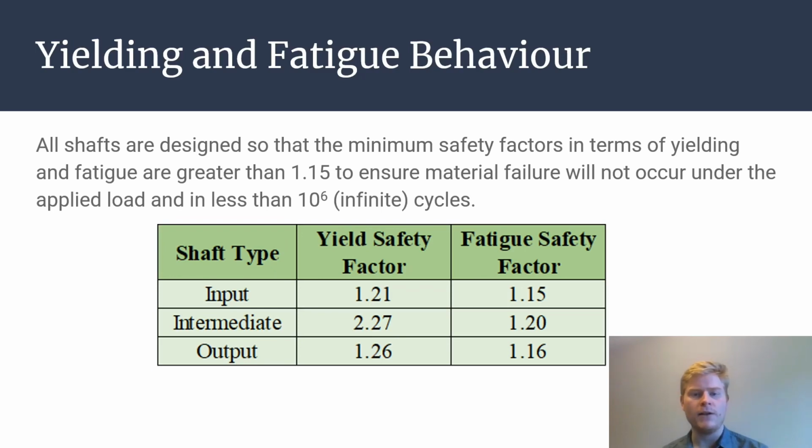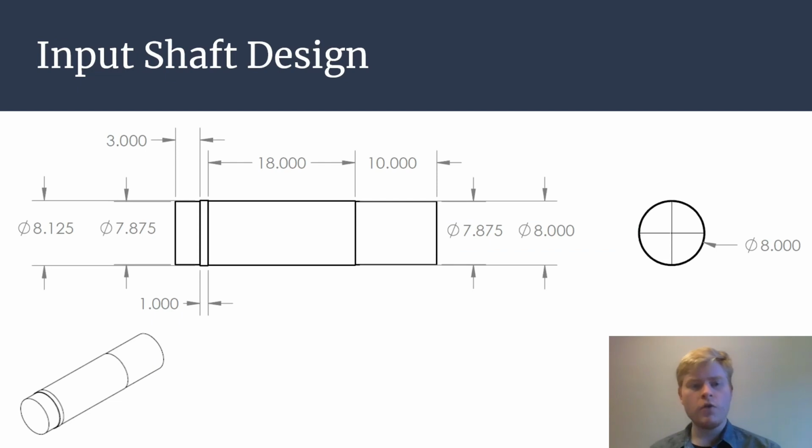1 megawatt of electricity. Moving on to the physical drafts of the components, all shafts are designed to minimize mass and to ensure the design is cost effective. The shafts are machined from high-strength AISI 4340 steel. The input shaft can be seen to have an overall length of 32 inches and possesses an 8-inch extension from the gearbox housing for the purpose of coupling to associated components.